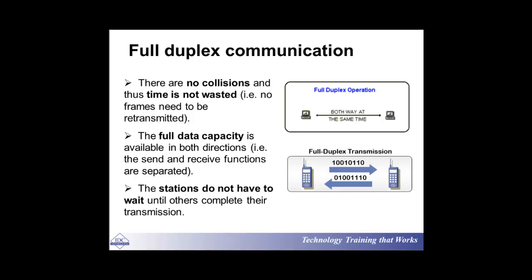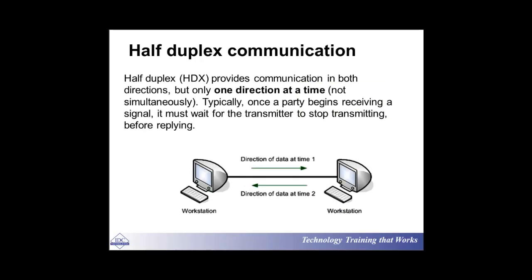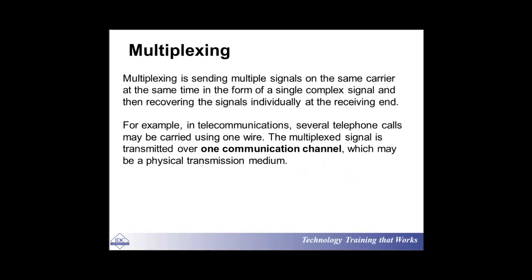So that can happen in, for example, two-way radio communication. That can happen in a telephone conversation, and that can happen in a substation automation system. So when you are thinking about 61850, most of the time you're thinking of a full duplex communication between different nodes if you would like to get the best quality for the 61850, right? So the way these stations are communicating to those data buses should be full duplex, so that at all times they are allowed and able to send the information to the other party. So that's one of the things with regards to communication.